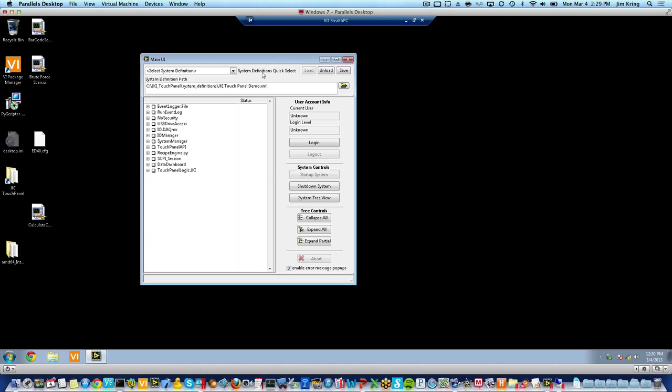And we're running the LabVIEW development environment inside of this production instrument, which allows us to very quickly debug. Once we're ready to deploy, we can, of course, harden things down, build executables, version them. Instead of Windows 7 Professional, we can run Windows 7 Embedded or apply the registry hacks like Matt was talking about, different things that make it a little bit more hardened, basically.